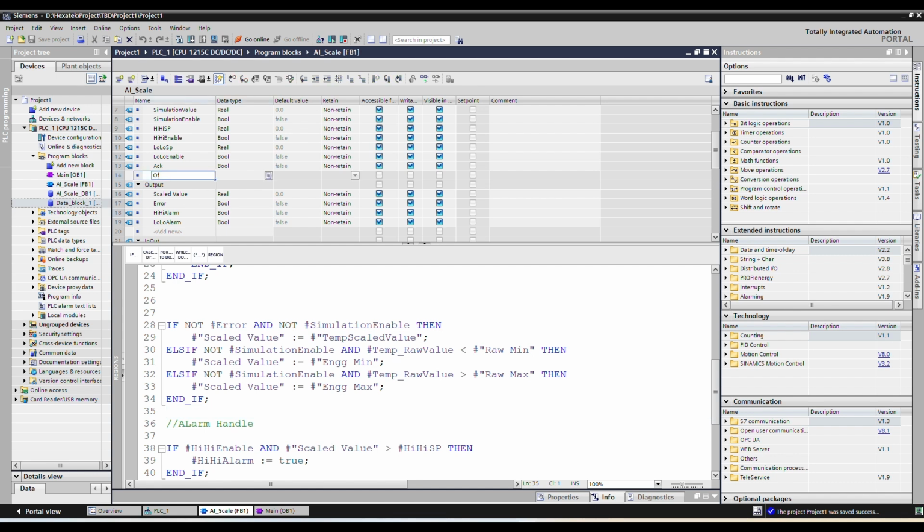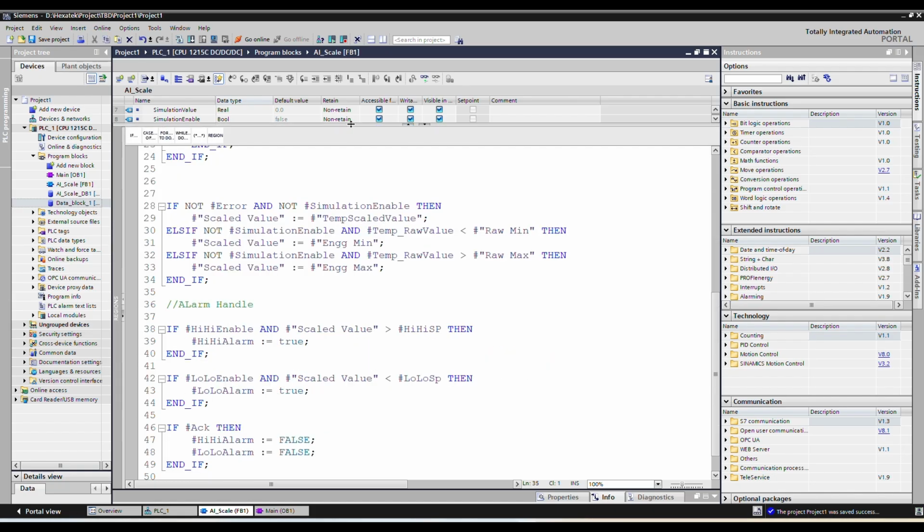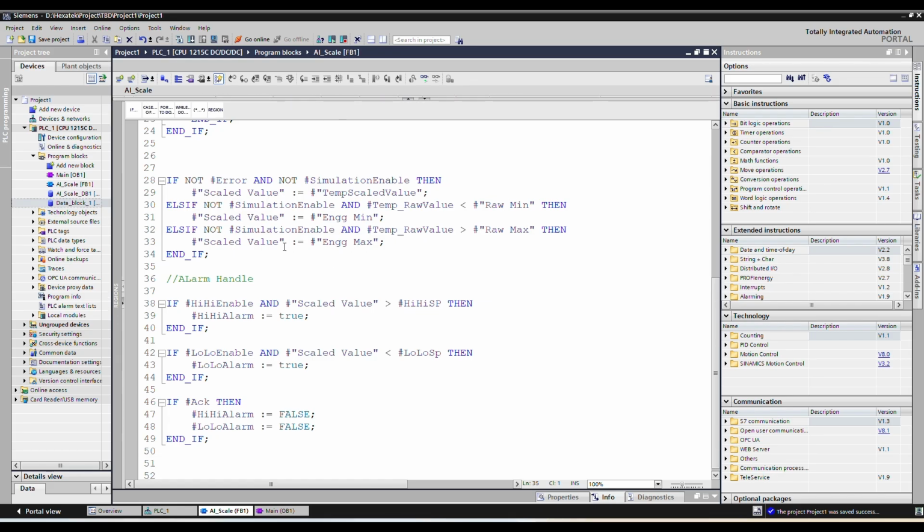Offset means, after some time, if the sensor deviates from the expected value, let's say the temperature range is 0 to 150 degree, but after some physical or climatic condition it is showing 0 to 151 or 0 to 149, this offset will help us show the correct value.